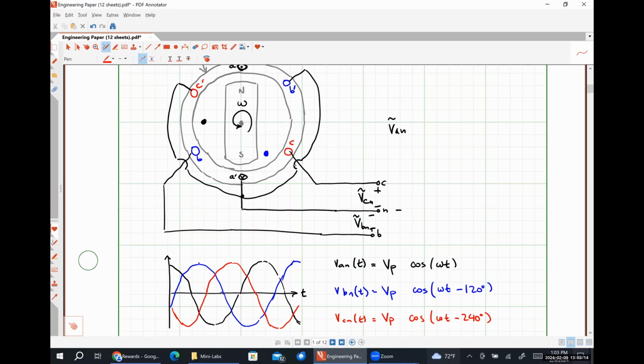So a 3-phase, 2-pole system like this, if we flip this system around to where this was a motor, this thing would spin here in the United States at 3,600 RPM because it's a 3-phase, 2-pole motor. If it were a 3-phase, 4-pole motor, it would spin at 1,800 RPM because it only has to go half a revolution before it catches the positive peak of the A phase again, like that. So anyway.